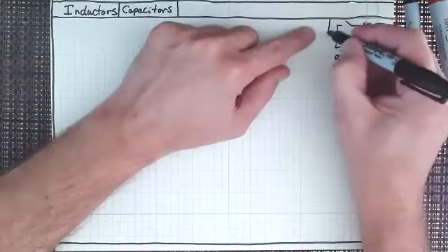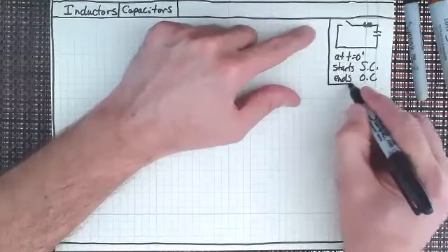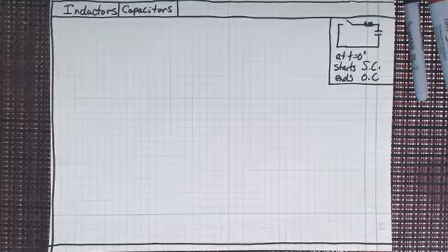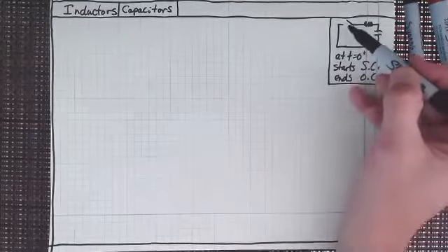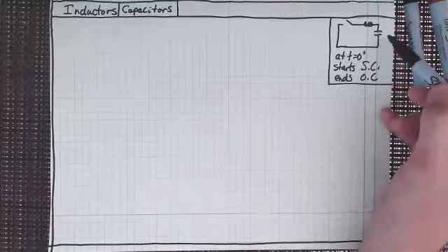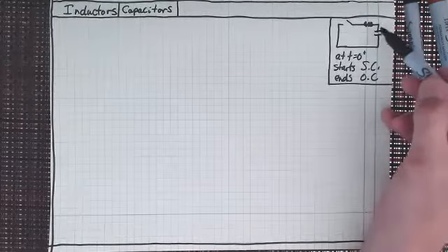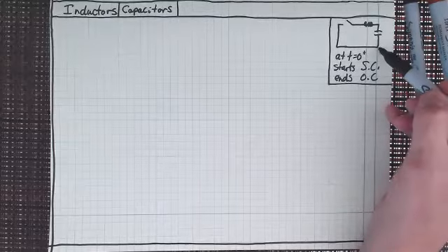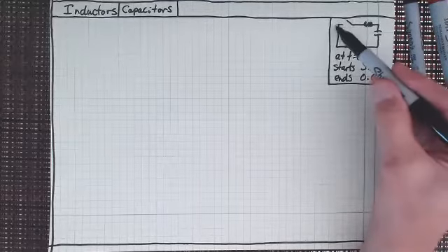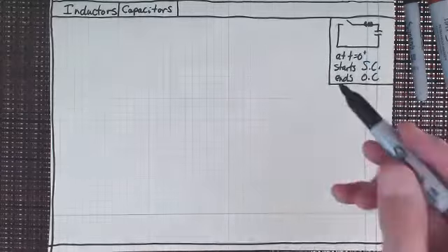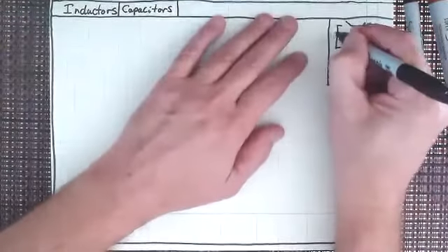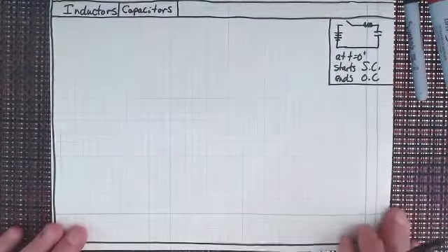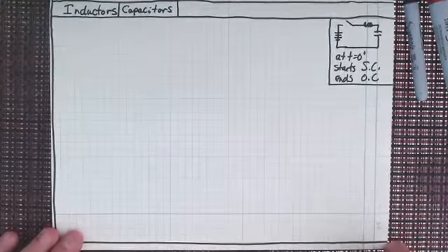So let's just box that in, because we've spent a lot of time talking about the fundamentals of a capacitor in a circuit and what it starts at, right? So as soon as the switch closes, this thing looks like a short circuit. It looks like it's not even there. It looks like it's just a piece of wire like this, right? But then after a period of time, the current is going to go from a maximum to a minimum. In fact, if we were looking at the current, let's put our power supply in there. If we were looking at the current, we see that the current is a maximum, right?